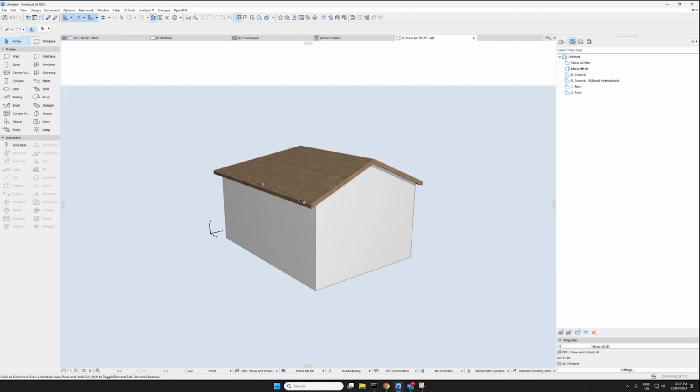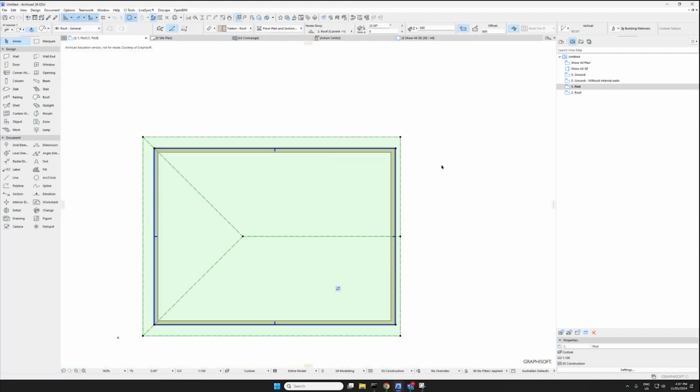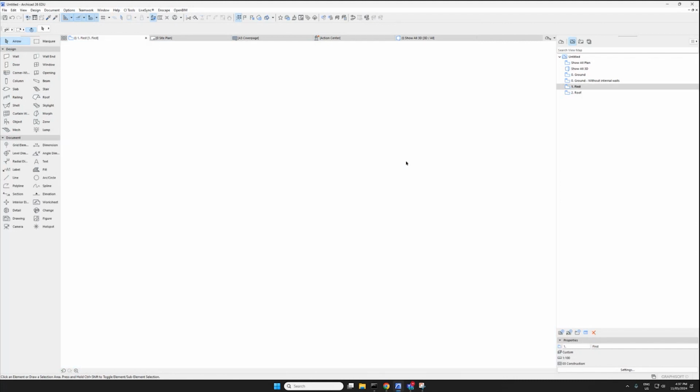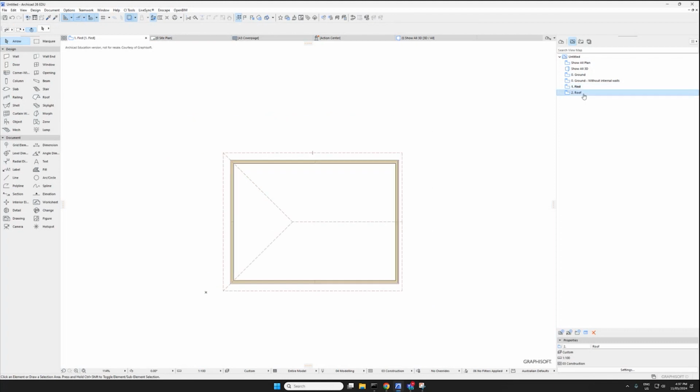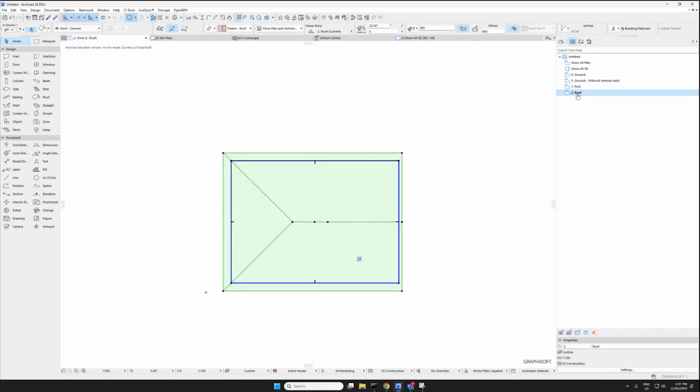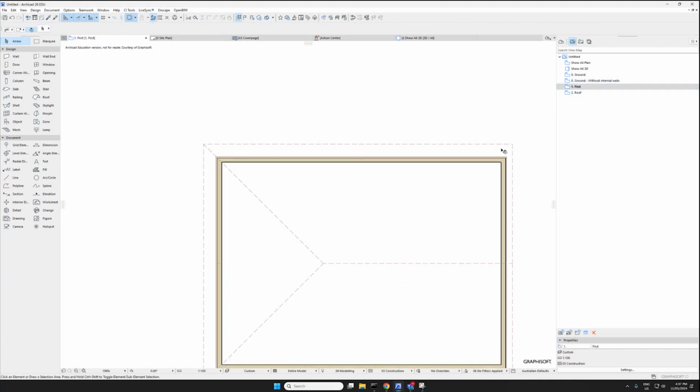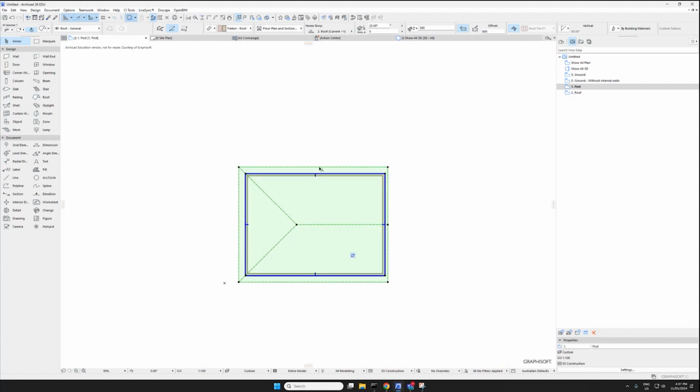So we can go into 2D view again by either clicking here or pressing F2. So F2 is 2D view, F3 is 3D view. F2 and F3. Okay. So see, we can see our roof on the first floor as well. We actually drew it on the roof plan, but you can make it show up on your first floor with outlines as well. Let's say you don't want to show that. You can right click on it and go to Roof Selection Settings, Control T. So good thing here, you've got all the shortcuts next to it.